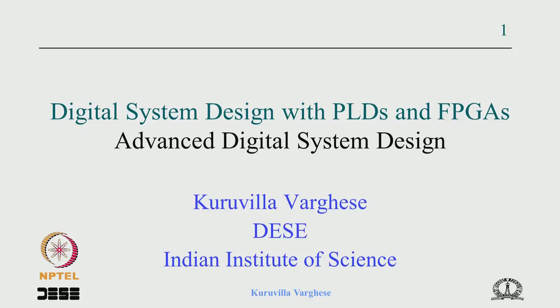In the last lecture we looked at the features of Mealy and Moore outputs, when we can use the Mealy output, and then we looked at the state machine controlling the data path through clock gating and recirculating mux, its advantages, disadvantages, how the power dissipation is, and a solution for it, and associated VHDL coding and so on. Today we will address some more issues of the state machine.